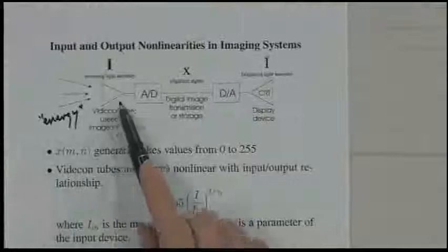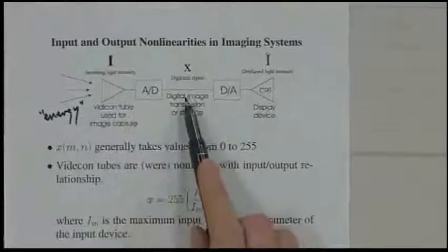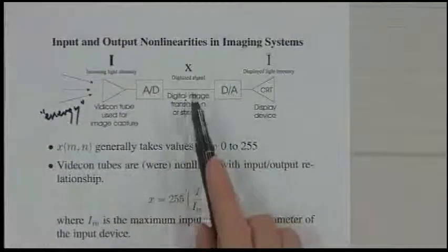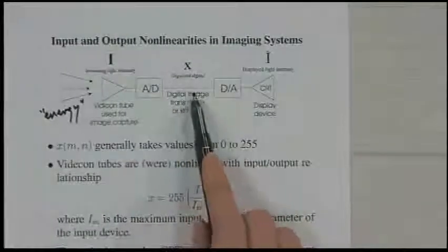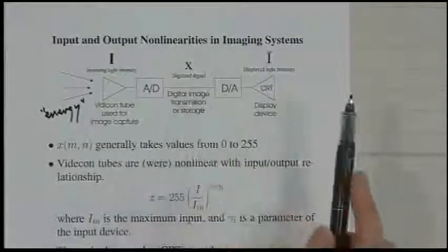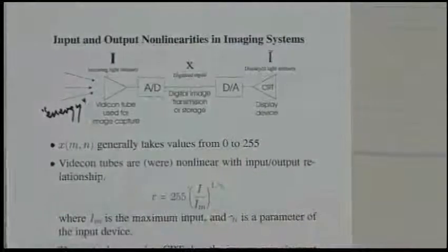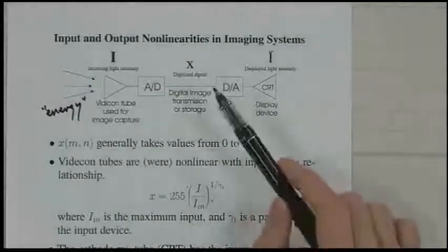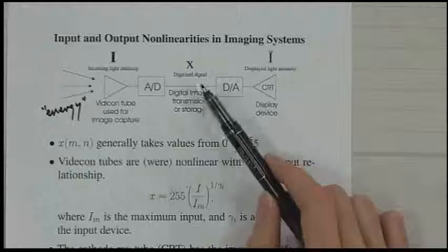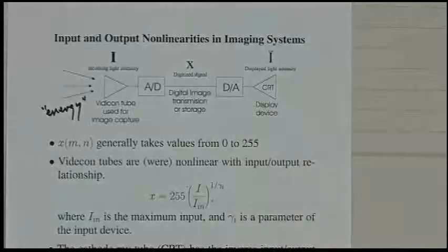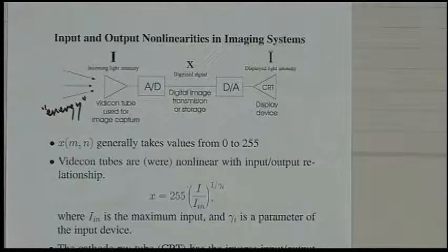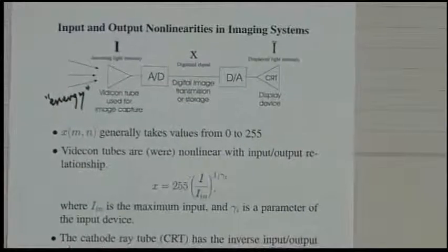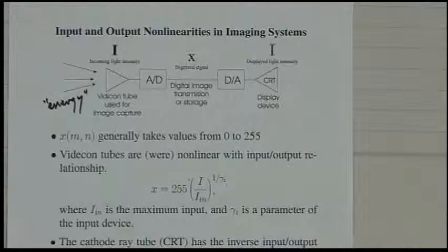And it just happened that the hardware applied a transformation where it essentially had that effect. And so the encoding here could be done very efficiently in that respect. So that's the main reason that gamma is still around and it will stay around. It's for encoding efficiency. There's no reason to allocate a uniform quantization in the luminance direction, because what we're really interested in are differences in contrast.